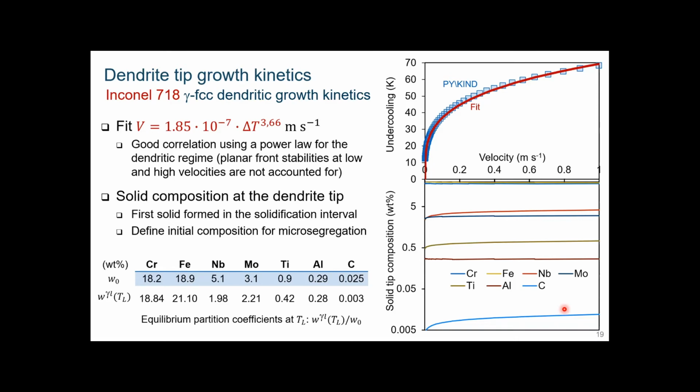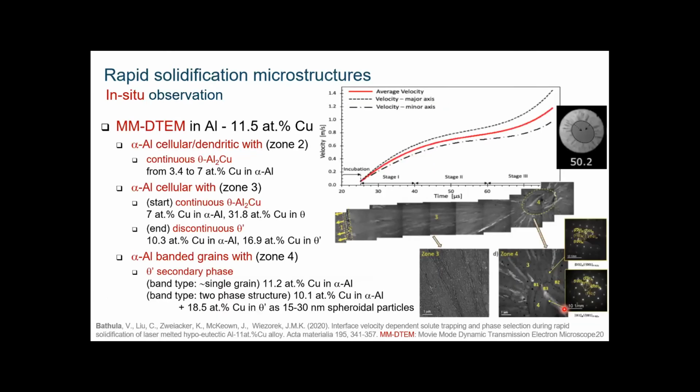So now comes the question, what about the effect of rapid solidification? Because you can imagine that at 1 meter per second, we may start to have effects that make the solid liquid interface depart from thermodynamic equilibrium. And this is what is observed recently. It's known for a while, but now we have in situ observation of the growth of a solid liquid interface up to 1 meter per second.